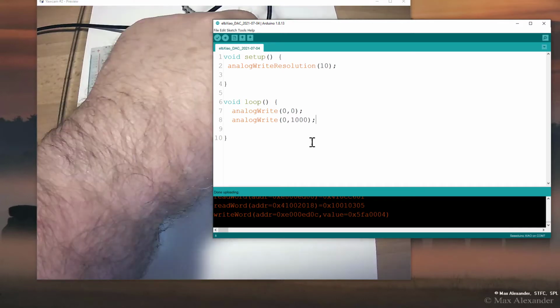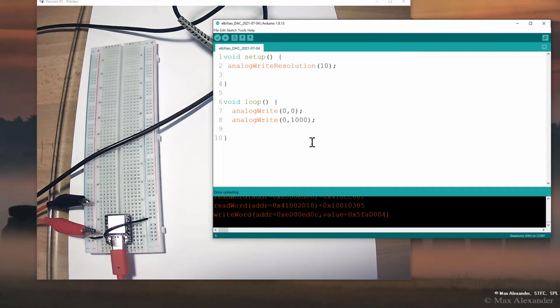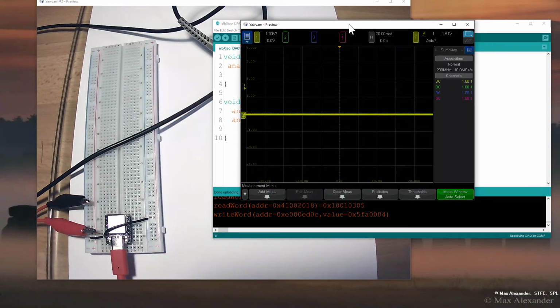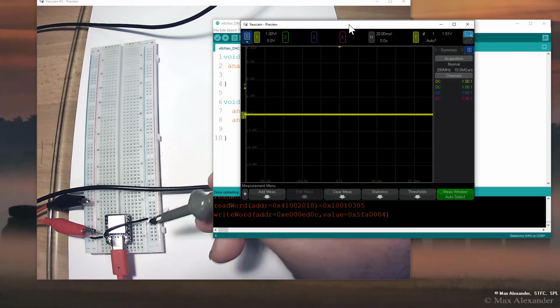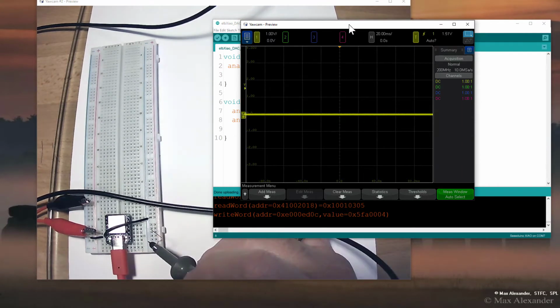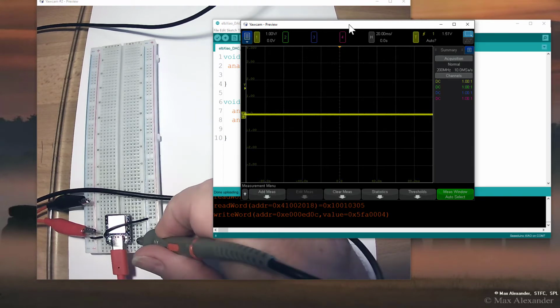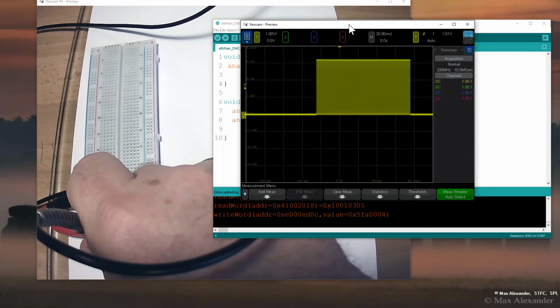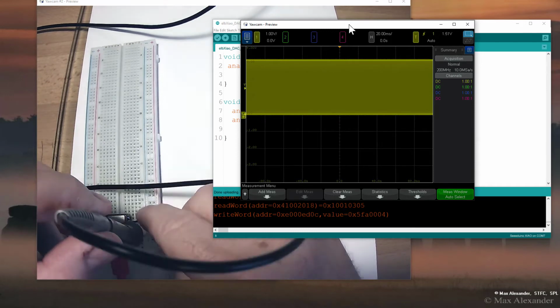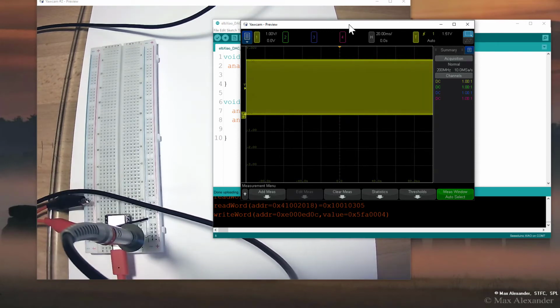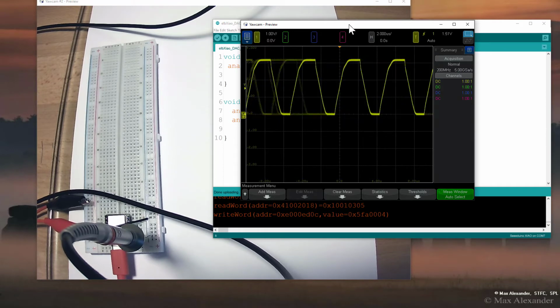First of all, I'm going to turn on the scope, and here is what is on the scope screen. I've got my 10x probe, and of course here's the analog output. This is ground, so we're going to stick the ground spring tip in ground, and we're going to stick the other end in the signal. There we see it, but of course, it's going really fast, so I'm going to expand the time base. Wow, there we go. And now we can literally read off the front screen how long the execution time is.